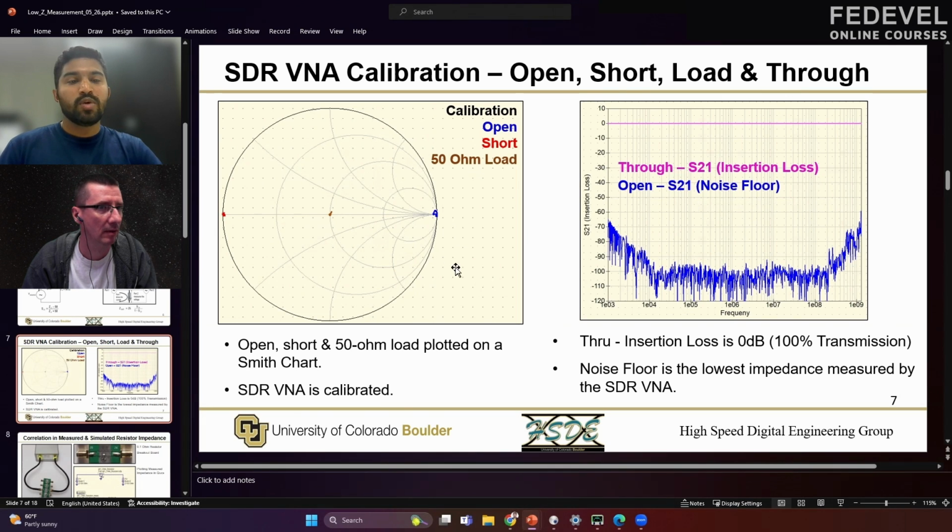Okay. So once we actually do the calibration and we have these consistency checks to understand whether the device is actually calibrated or not, now we are confident in the 2-port method. We know that our device is calibrated. So let's actually move on to the test setup and measure something as simple as a 0.1 ohm resistor.